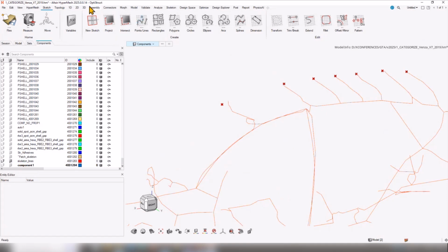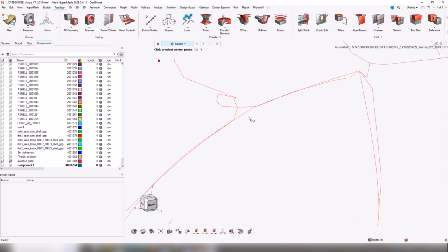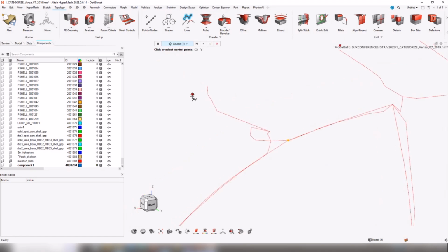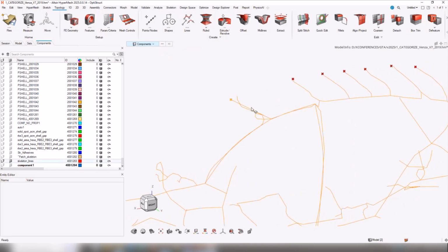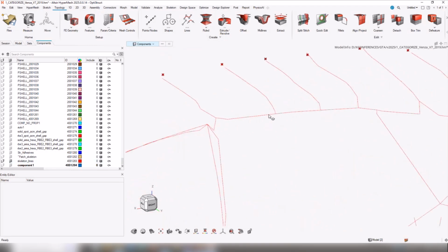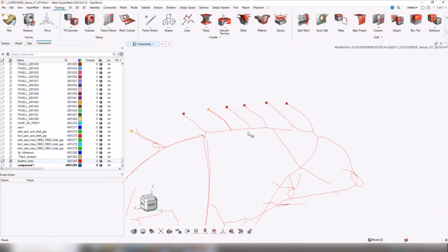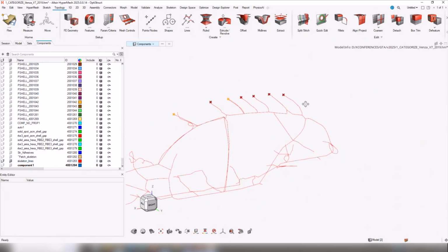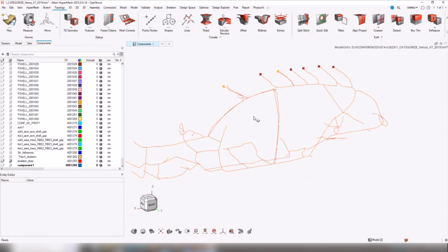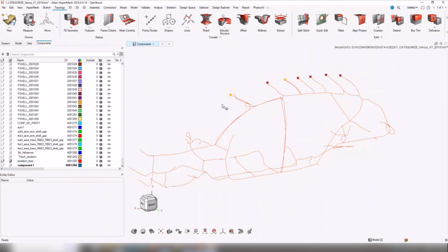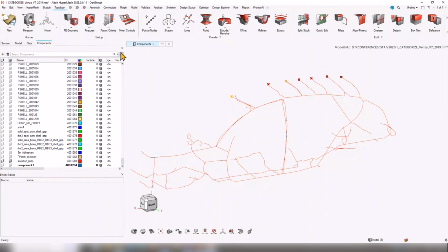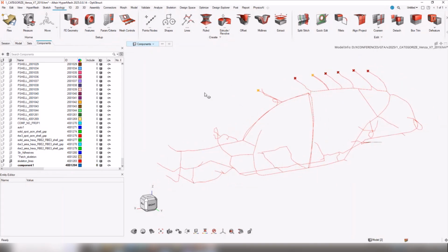So now I would go back to topology again, polyline, and then wherever the snap point was here, I could just now go and leverage that directly. I'll probably need an additional control point in that, but you get to see how leveraging the sketcher and the intersect, we can actually create a much more clean and detailed representation. Okay, so this would probably take 10 minutes to clean up, maybe a little bit longer, but yeah, using the sketch and the polyline with this mid-plane extraction, that's one approach.